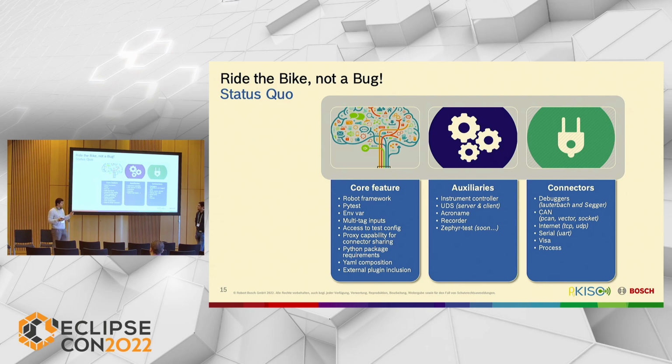The recorder is simply, like the name says, recording something on a specific bus or a specific connector if you give it a connector. And that also enables you, if you have a test and you wait for a warning message from your device, to give it the information to parse, and when this warning message is there, you can use it to validate your test or say it's a failure.